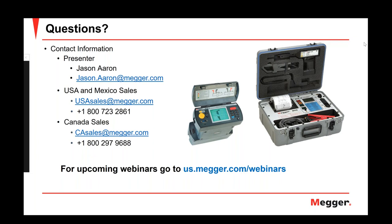All right, thanks, Jason. Sanket, for strap resistance and battery impedance, is it required to have the 72 hours float / no water added? Yes. The reason why that is necessary is because we want the cells to be in the fully charged state.